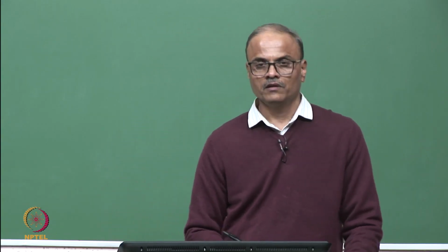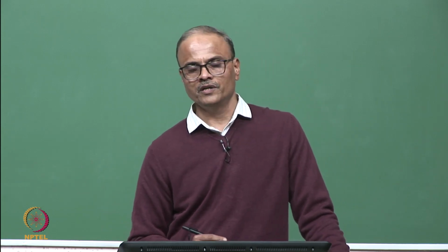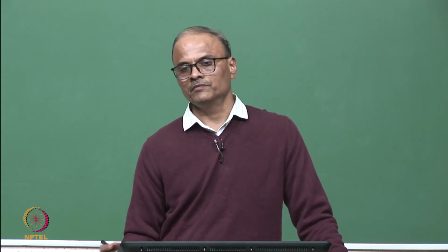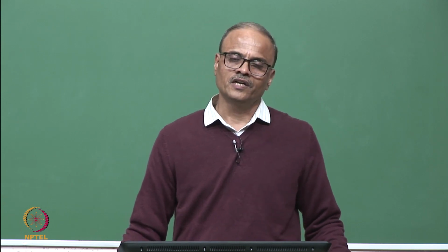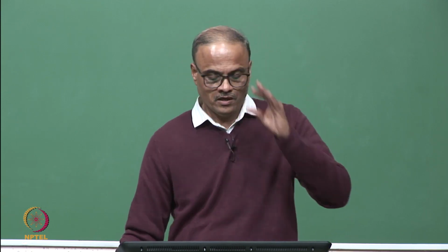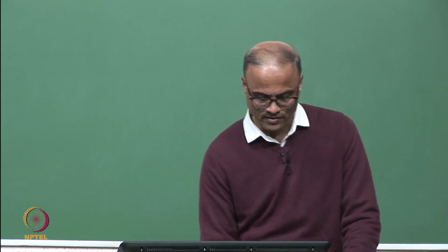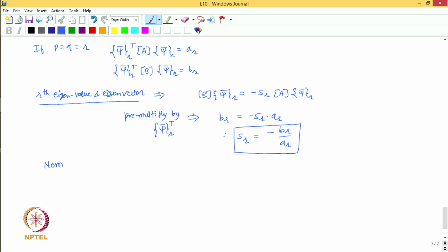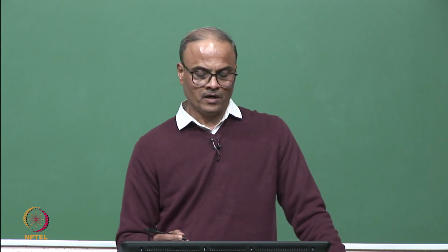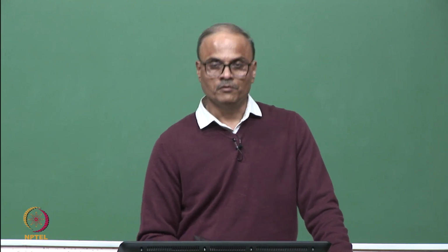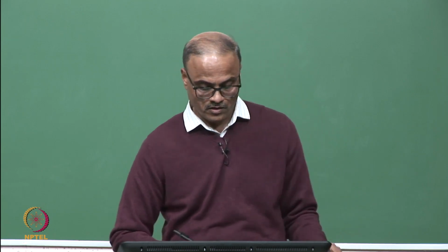So, let us see how we can normalize these modes, these eigenvectors. Currently the eigenvector psi bar R is scaled arbitrarily, there is no unit scaling. So, let us see how we can normalize that. So, normalization of eigenvectors. We would like to normalize the vectors such that the value of AR becomes 1, similar to mass normalization we studied earlier.